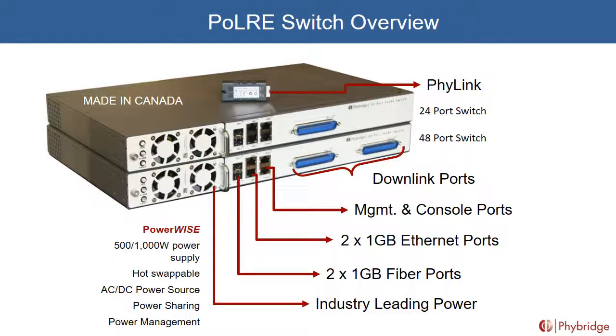That 48-port and 24-port connector is the one that's already there for the legacy telephony. And so this is really a plug-and-play technology rather than a rewiring technology. Is that correct? That's right. If you recall from our slide at the beginning, the RJ21 connector, or the Amphenol, is the same connector that's on your legacy digital or analog line cards that you remove and plug right into our switch. So no recabling required, plug and play.